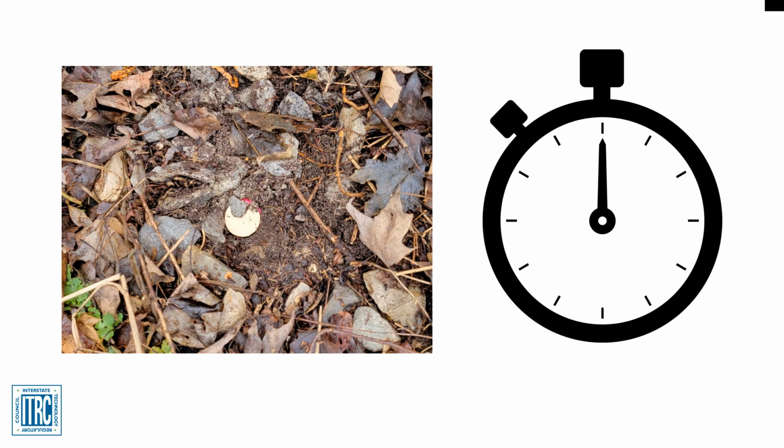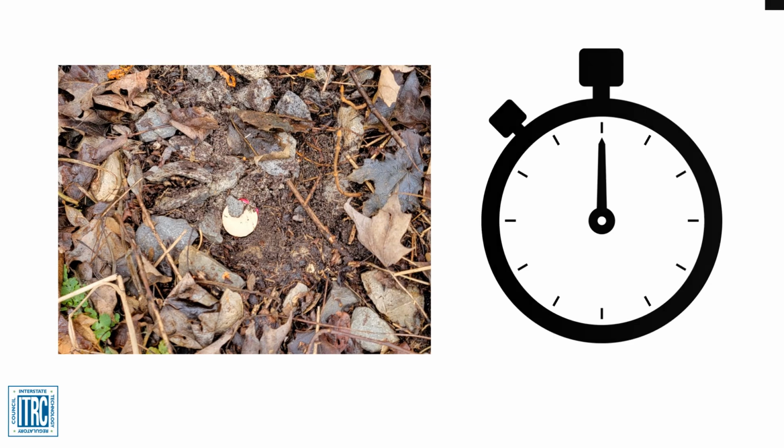First, remove the cork by hand or with a pry tool and pull the string up to remove the sampler from the boring. Once removed, the string is cut. The sampler is wiped clean using a clean cloth rag or paper towel, returned to the corresponding glass vial, and logged onto the provided chain of custody. The samples are packaged and then can be shipped to AGI's laboratory for analysis. The AGI modules do not have to be kept cold for shipment.